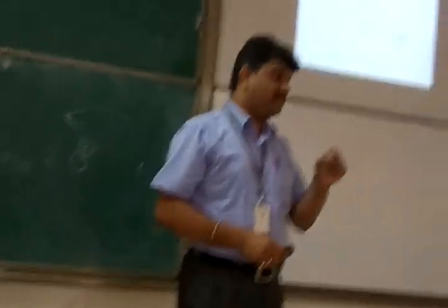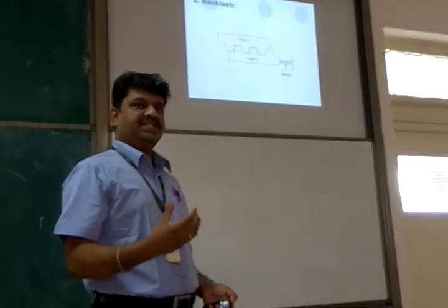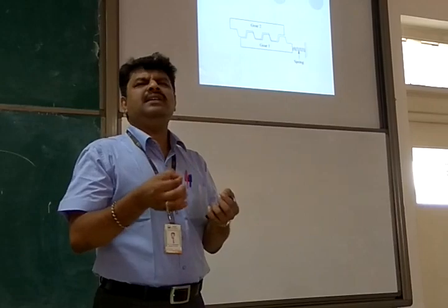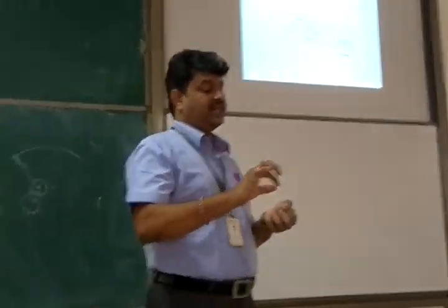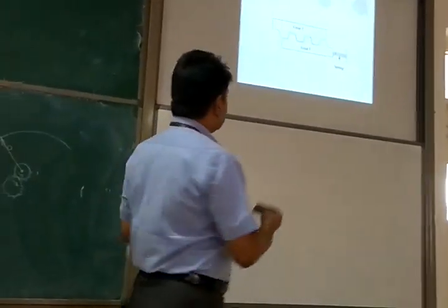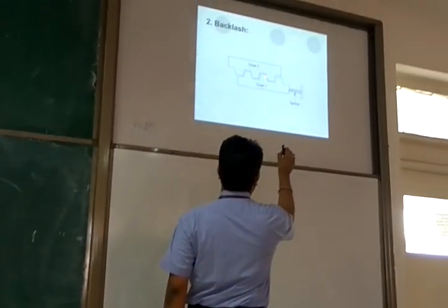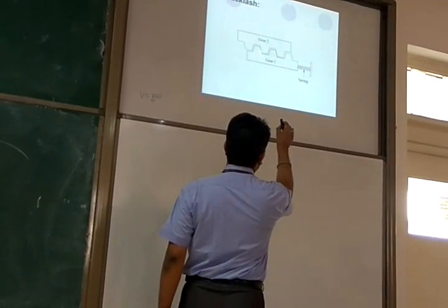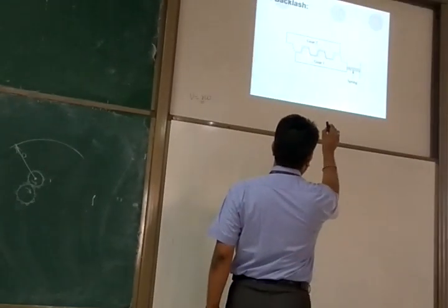Now, I have put a light spring. It's very important that it should not be a very heavy spring, but a very light spring. That's why in watches as well as in gauges, you will see a very thin spiral spring. One end is attached to the body, the other end is attached to the pointer or the gear which is rotating. That spring will always keep them in contact. Gear 1 is always pulled against gear 2. See, there is no gap between the two surfaces.